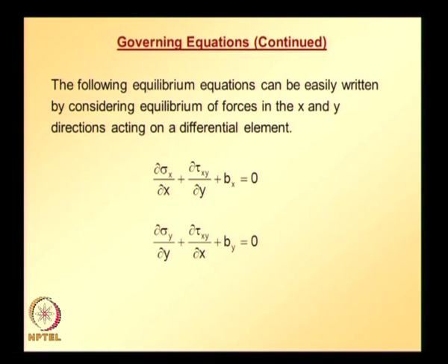So, now what we need to do is express these equations in terms of displacements, because displacements are our primary variables which we need to solve. These equations can be expressed in terms of two displacement components, because we are looking at a 2-dimensional elasticity problem: u along x direction and v along y direction.